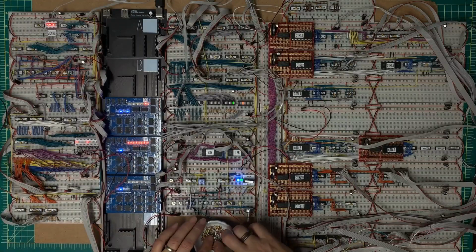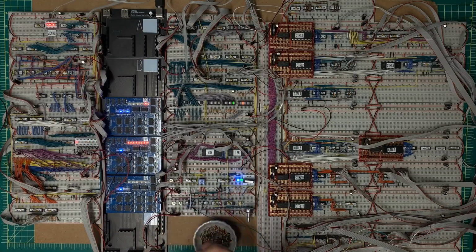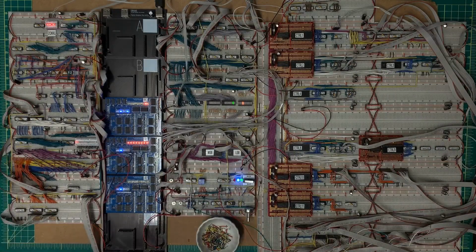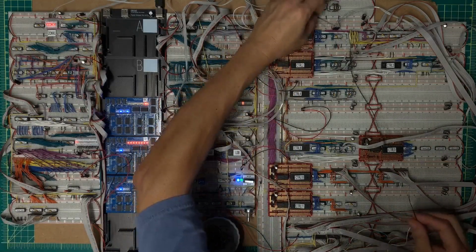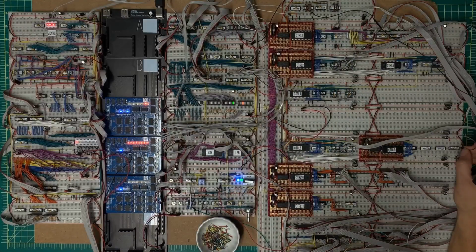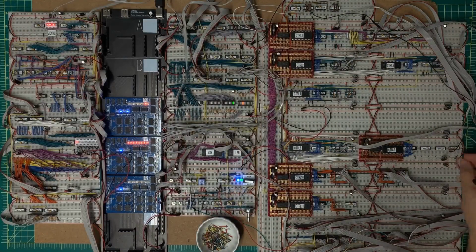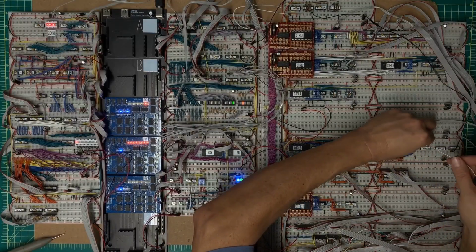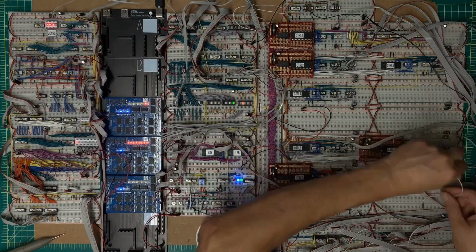So this now means I need to spend a minute hooking this up. And then the signal I want to take is this clock signal. I'll be able to stick it in here. Now that'll be the least significant bit. So that's coming off of the latch here.